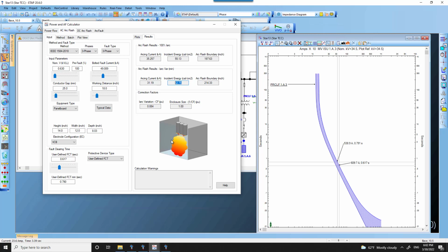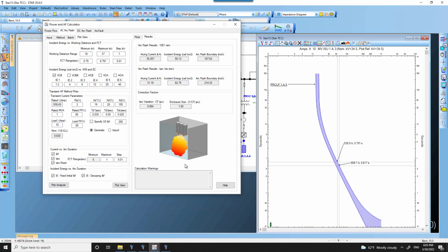So we used our ArcFlash power tool calculator, and we are able to get a trend, given the fact that the fuses cannot be replaced because of the cost and the budget of the project. The next mitigation technique to keep the existing system conditions is to use the incident energy evaluation based on a different working distance. That is when we have the plot view feature in ETAP,